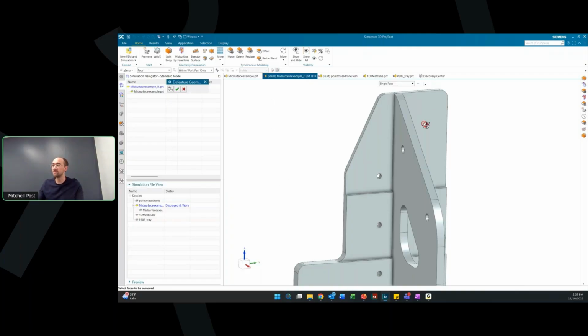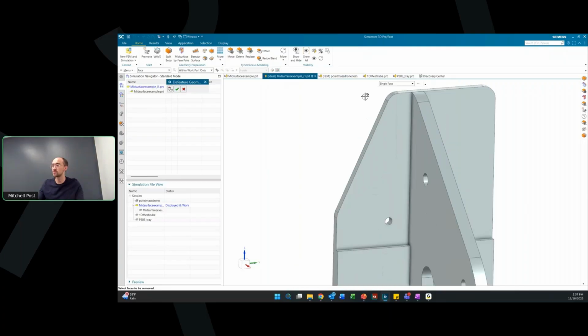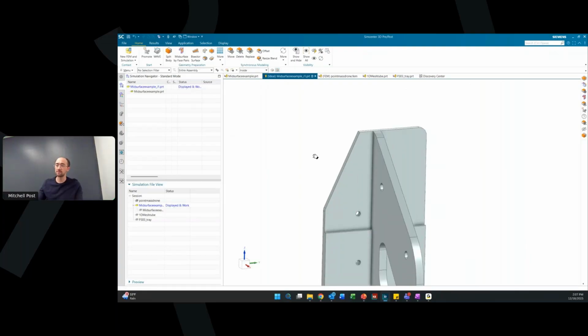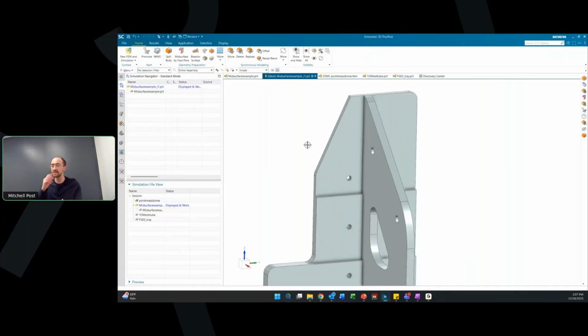So you can also use deep feature geometry. This works with holes, this works with fillets, this works with some other geometry. You can play around with this if you want. But these commands have the same function to some degree, but a lot of them are a little more specialized. So if you're having trouble working a command, you can always try a different one, because I guarantee there's another route to take when you're trying to get to a certain result.